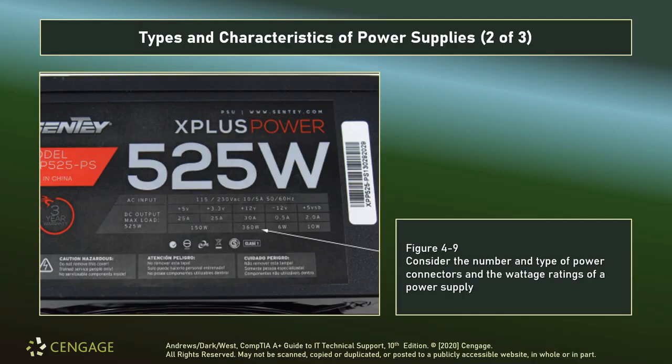That's the AC input. The DC output, we would expect to see maximum load of 525 watts. So we can see the big 525 in the model number, we can see the big 525 on the sticker, and we can see that it's also declared under the words maximum load. The 5-volt rail, standard 5, runs at 25 amps. The 3.3 also runs at 25 amps, and the two of them together, that's why they're kind of boxed in that group, is a maximum of 150 watts of power altogether.